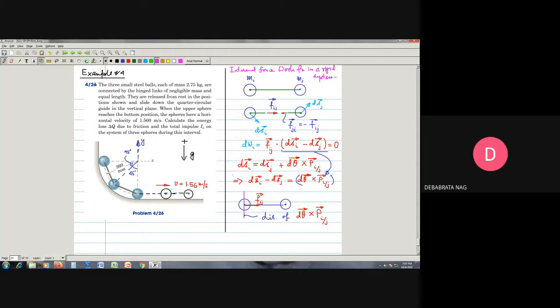Once this is done, we can now come into this problem. Here we have two rigid systems again interconnected, and we can forget the work done by the internal forces which will be developed through the forces in these rigid links. We can just consider the work done by all other external forces.